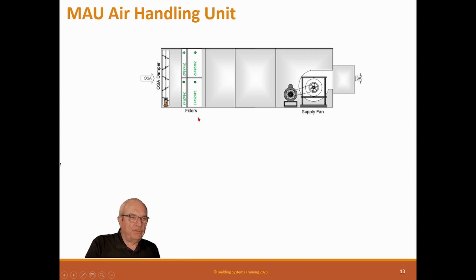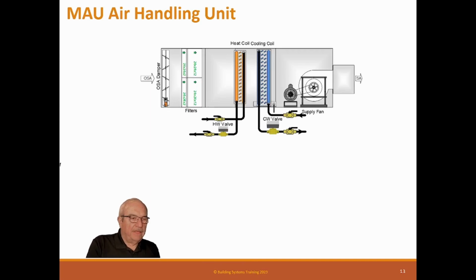So this is a makeup air unit. Now, a makeup air unit is similar to a DOAS unit, except it's not trimming off outside air. It's actually providing makeup air for some kind of process. Might be a kitchen hood, might be a laboratory making up for biohoods. It could be for an industrial process making up for fume hoods or capture hoods, or it could be some other space that's making up air for something that's affecting building pressure. So basically, these are the makeup to prevent screwing up building pressure.